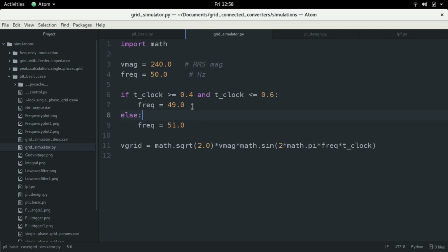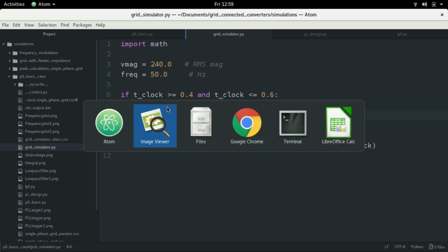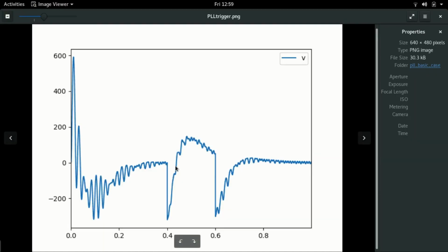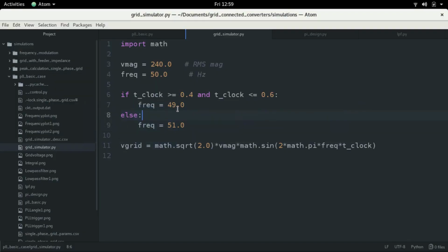Typically, when there is a case of load increasing, for example, as during the day the load keeps on increasing, let's say in a summer month as everyone is turning on their air conditioners, the frequency will gradually decrease. So you won't see such a drastic jump, you'll see a gradual drop. And therefore, we do expect in such cases that the frequency will be able to lock on continuously. So I would recommend that besides also trying to do this, try to code a gradual change in frequency as well, right? I'll leave that to you as an exercise.